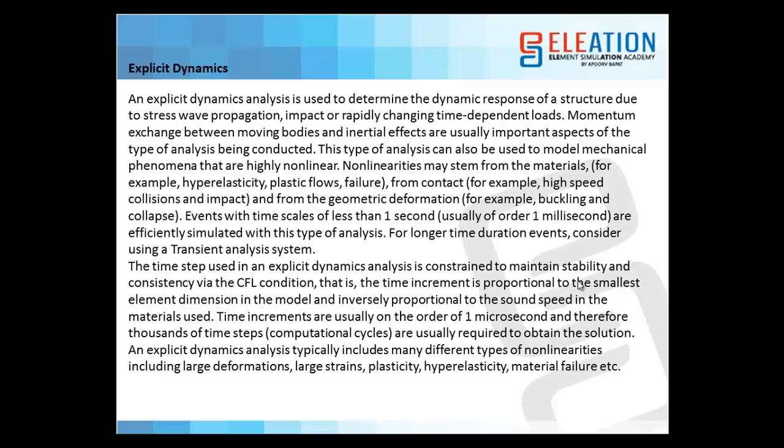in dynamic analysis. Events with a time scale of less than 1 second, usually of the order of 1 millisecond, are efficiently simulated with this type of analysis. For longer time duration events, consider using a transient analysis system. The time step used in explicit dynamic analysis is constrained mainly to maintain stability and consistency via the CFL condition, which we will see later on.